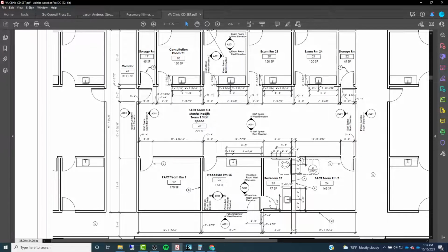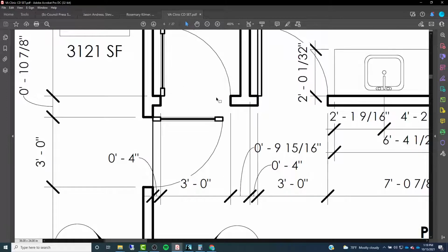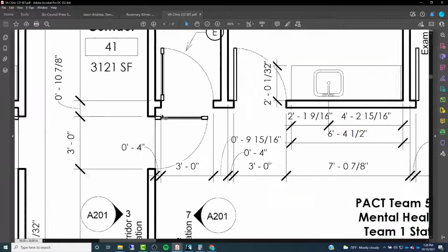If you recall from the Digital Apps 1 course 2, I think we covered door tags then. Basically that would be just an oval shape within the door opening that's going to indicate the door number and the door type, which then is going to tie to some sort of a schedule that you could refer to, and that's going to tell you exactly the size of the door, the material of the door, all that kind of stuff.